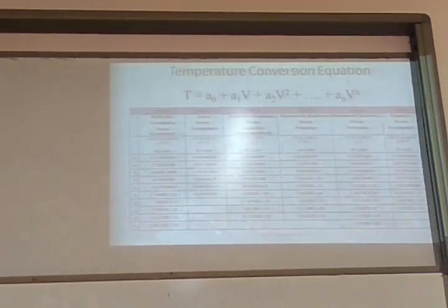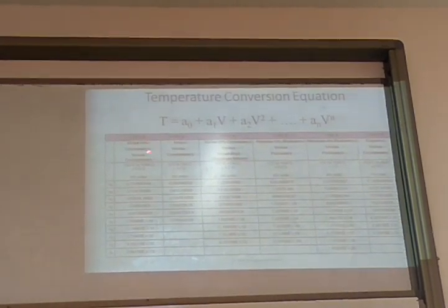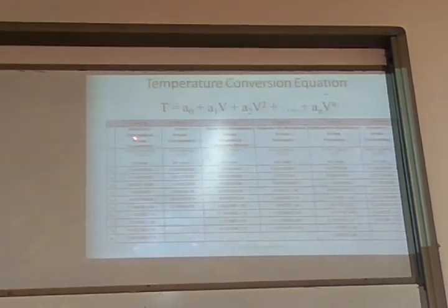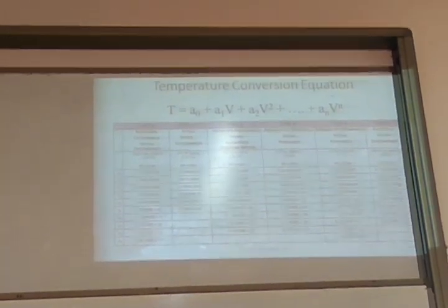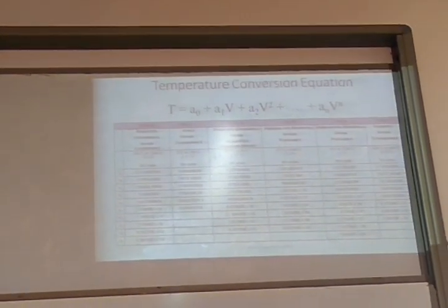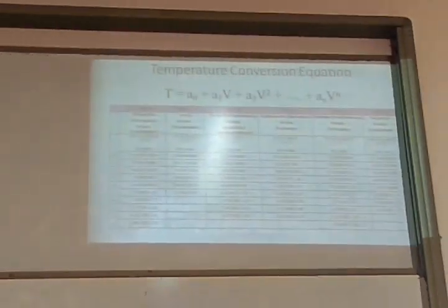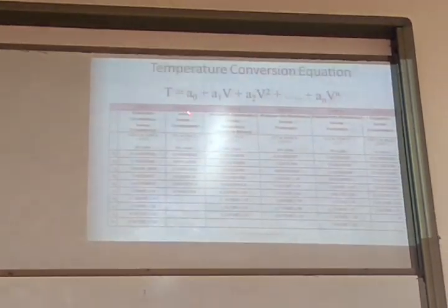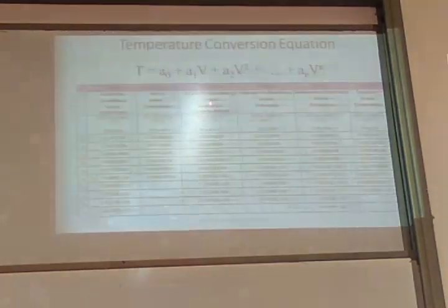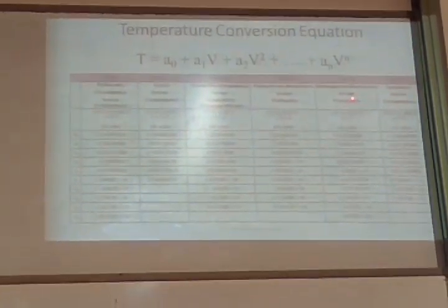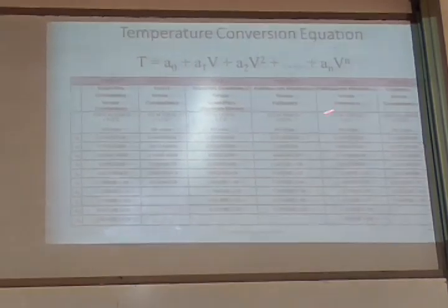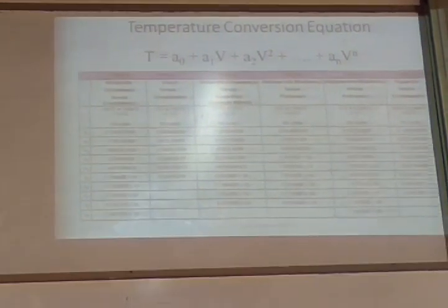Yeah, this is what I was referring to. I was searching for this one. See, this is nickel chromium, if I use it as a thermocouple material. This is called the E-type thermocouple, and that cost is different from iron versus constantan. This is nickel chromium versus nickel. This is platinum rhodium versus platinum, of course with different compositions, and copper versus constantan.